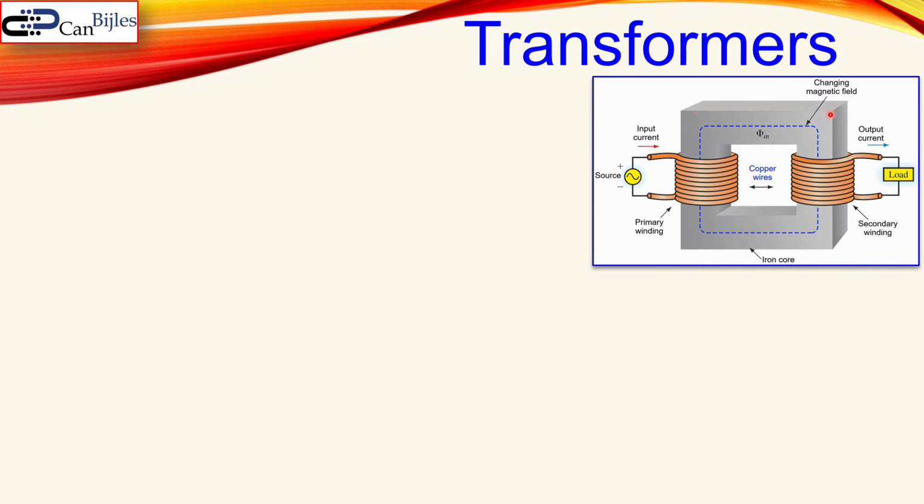What you also see is that this is electrically isolated, so you don't see any electrical connection between these two wires. Now, of course, we need to look at the characteristics and use a symbol, and also develop the equivalent circuit to use that in our design. As said, this provides electrical isolation, which is very handy. And it produces step up or step down time varying voltages and currents at the output. That's the brief discussion of this transformer. So we'll see shortly the formulas also. There will be a relationship between the number of turns in both windings.